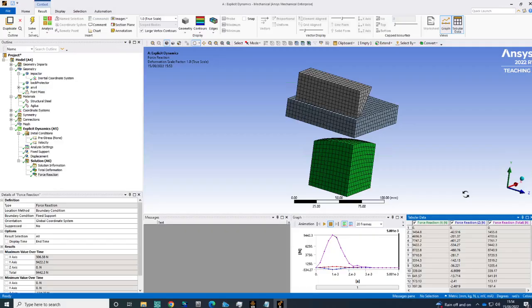standard. So what usually happens is that manufacturers make holes inside this structure, make it hollow, make it from lattice, etc., in order to increase the compliance, reduce the stiffness, and increase the energy absorption. But I hope that this example has helped us to review all the theory that we have seen in the lecture and learn how they can be used within one package, which is ANSYS here. Thank you for your attention.